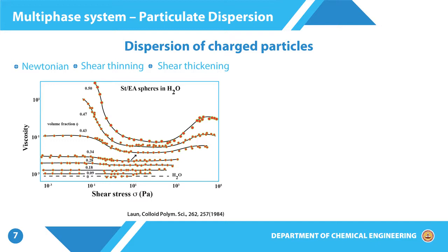So, this would again imply that at higher strain rates or higher stresses, there is again a tendency for particles to aggregate once more and form clusters, and these could be due to hydrodynamic interactions, alignments, or jamming. So, there are several features which can cause, at higher strain rates, the particles to again percolate, and then viscosity can increase again.